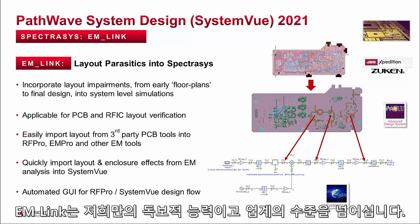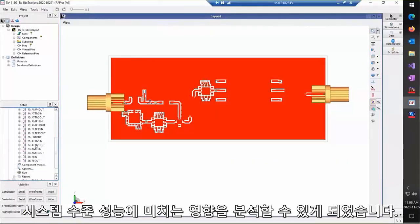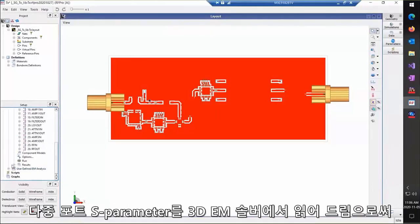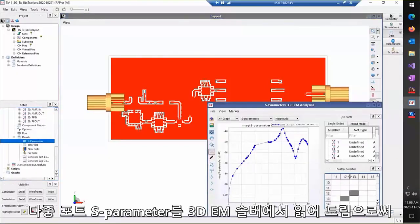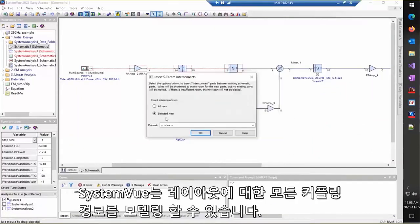EM Link is a brand new capability that has no equivalent in the industry. For the first time, system designers can analyze the impact of prototype board or enclosure designs on their system-level performance. By reading in a multi-port S-parameter output from a 3D EM solver, SystemVue can model all the layout-dependent coupling paths.